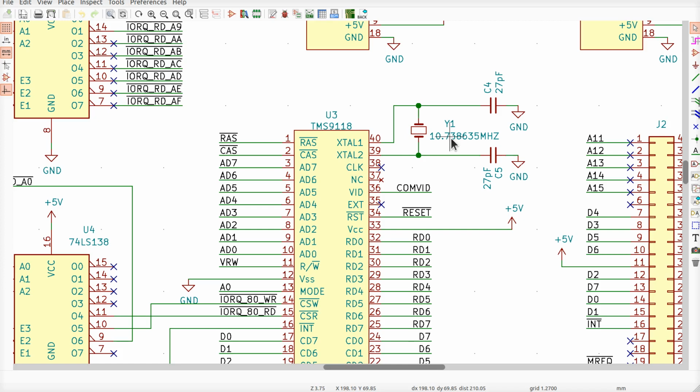Keep in mind that this is a completely autonomous and different oscillator than the one that's running on the Z80. These cannot be synchronized. Absolutely not going to happen. They'll slowly drift in speed and they'll walk around relative to each other a little bit, okay?